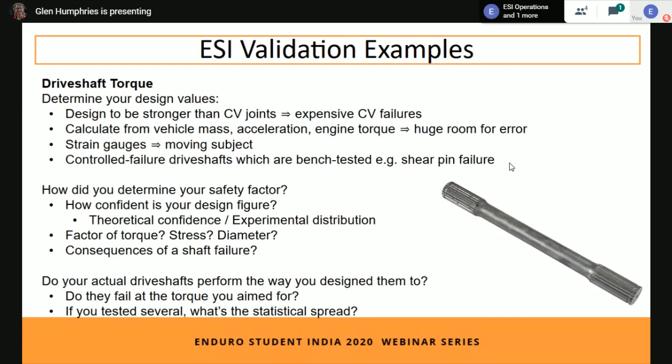And of course, when you're determining your safety factor, what's the consequence of failure? Is someone going to die if this thing fails? No, probably not. But you might be knocked out of endurance, or you might fail one of the earlier events, acceleration. You might be knocked out of endurance either permanently or for 20 minutes, an hour. So you generally don't want this thing to fail. But because you don't have a life riding on it, like you would with the rock climbing safety gear, you probably also don't need a 15-to-1 safety factor either.